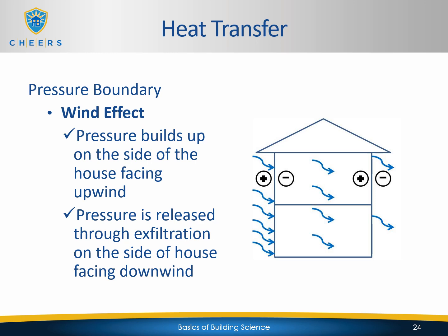Through infiltration points, air is going to leak into the house and push through to the right side of the house, creating positive pressure, and that is going to get sucked out to the outside, because that's the direction the wind is going. On top of that, because wind is being pushed all around the house, it's going to create a wind tunnel around the house as well. The wind tunnel is going to pull the cold air from the right side of the house as well. And again, it's going to perpetually go on until we stop it by creating a proper pressure boundary.